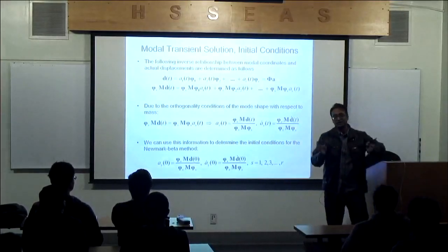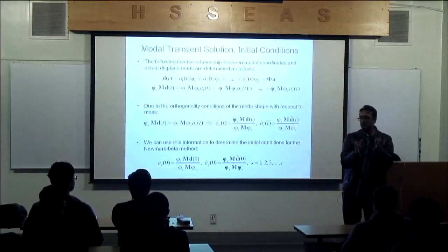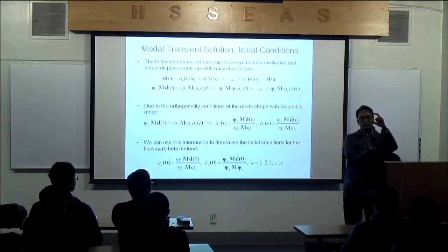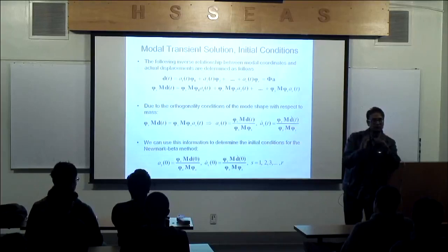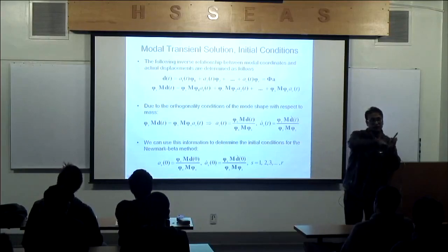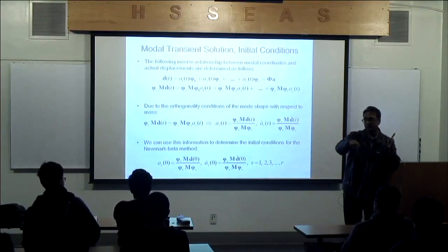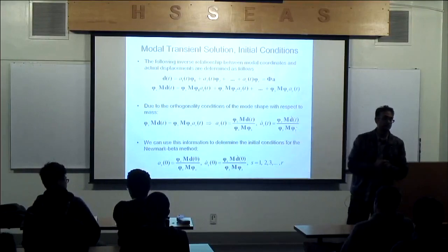Now it goes back, guys, to just the elementary spring, mass, dashpot, fixed, oscillating mass. So if I know the initial conditions for velocity and displacement, now all I have to do is calculate how that vibrates, and I get the amplitude A. If I get the amplitude A, what do I get? From the mode shapes, isn't this amplitude the multiplying factor to the mode shape? So I get the displacements as a function of time.